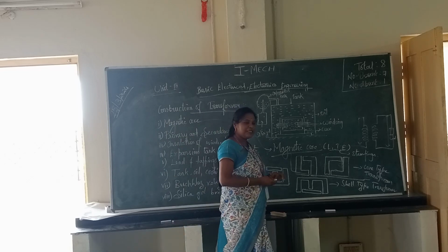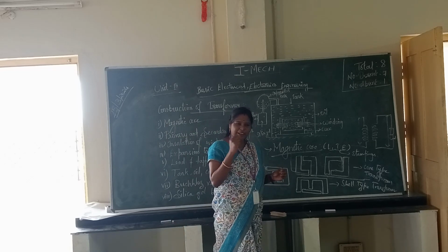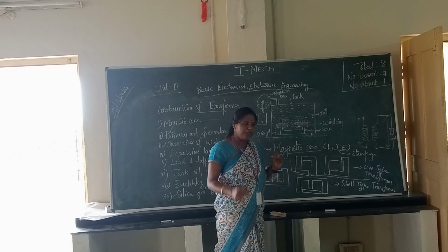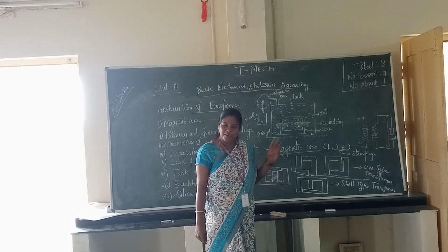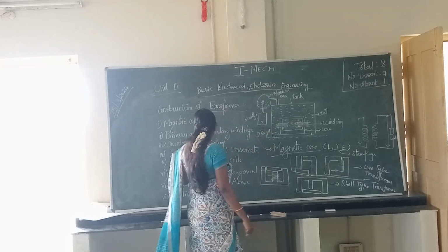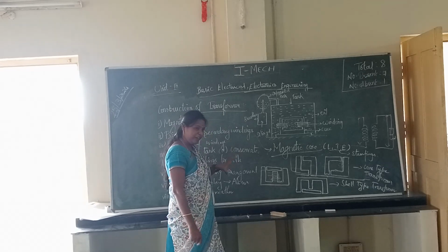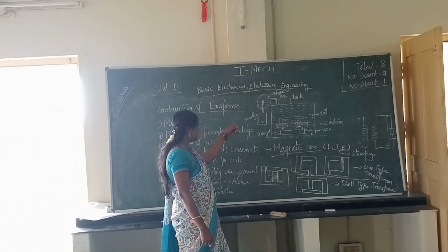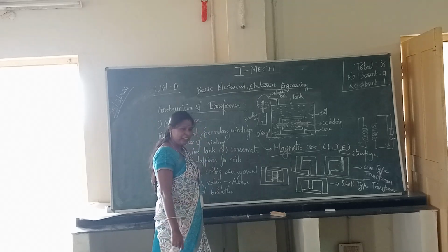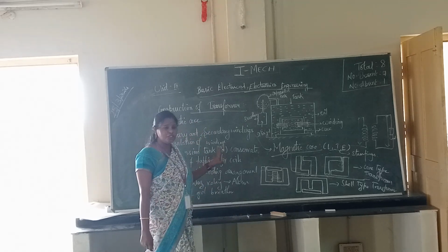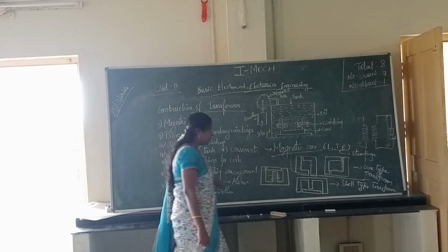So I think primary and secondary winding are not clear. We use thin copper wire to give a winding in the transformer. Okay, copper thin wire is used for the winding purpose. Okay, next is insulation. I told we use paper insulation between the windings. Okay, and expansion tank. You know what is expansion tank? Everything is clear, right? And cooling arrangement and the relay and all is not shown here, which is used in the bigger transformers. Okay, right?